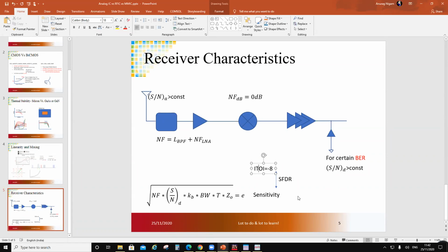Okay. Now, if I am assuming that it is a thermal noise, so this basically is a thermal noise. This is true if this is a thermal noise. What if there is a noisy environment over here? Then in that case, you will not take the thermal noise, but you will take the signal strength here of the noise. And in most cases, if the noise is very large, I will not use LNA because the mixer is going to compress. So I am going to throw out LNA. I am going to just use a mixer. That happens in most of the radars.